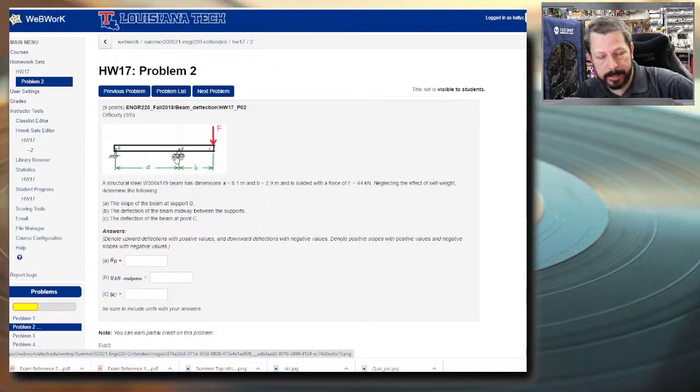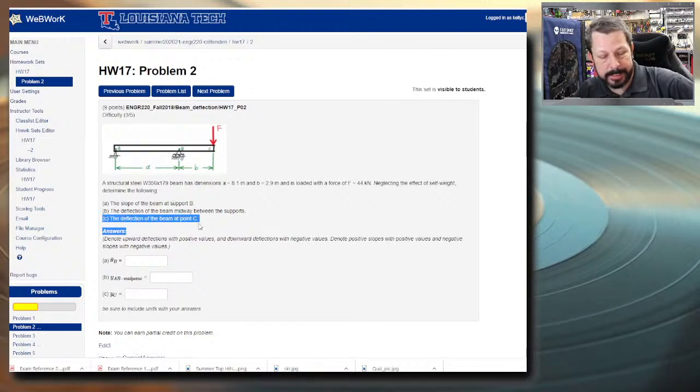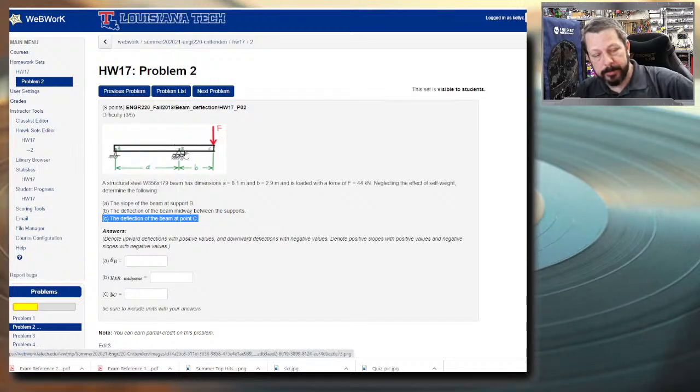So a moment here, F times B at point B. So this force times this distance is the moment at B. And that works for most things. It did not work for part C, because if you apply a moment here, this part of the beam BC would just be deflected. It would just be angled downward. But there's really a point load on the end of it, which makes it bend the entire length. And so we worked that one.